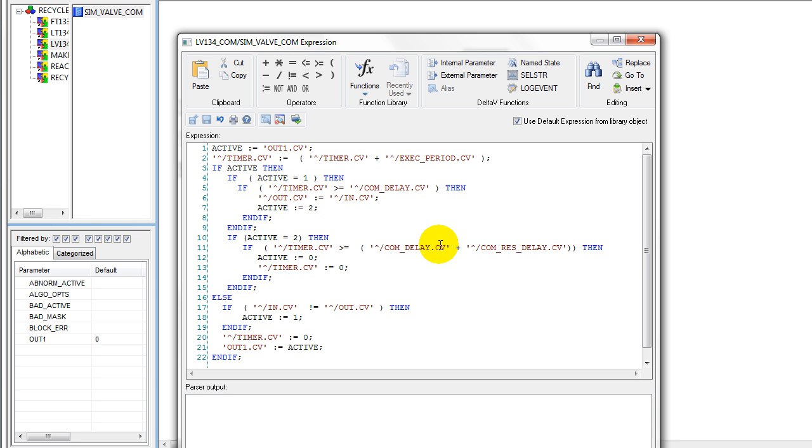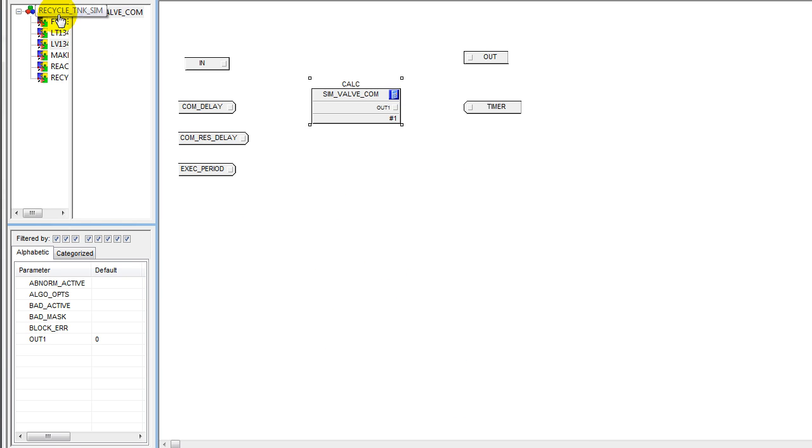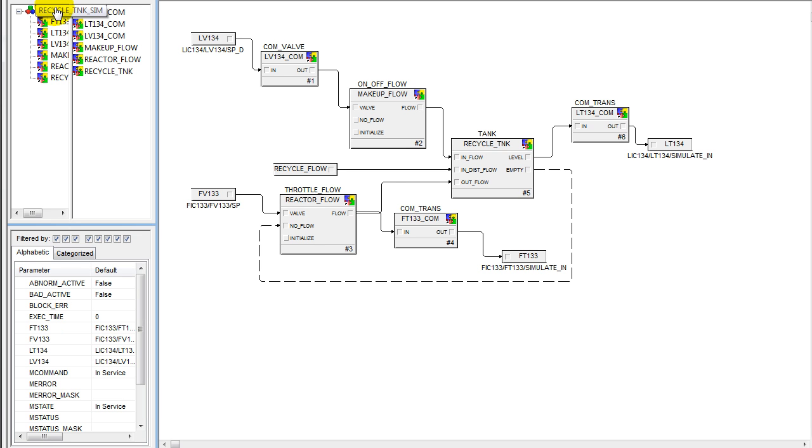Once we have made the change, then we wait for the response delay before we allow another change in the output, and that is what is shown here in terms of the simulation. As you can see, that can be implemented very easily in most DCS systems.